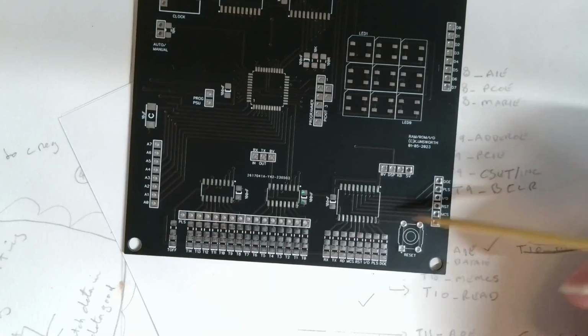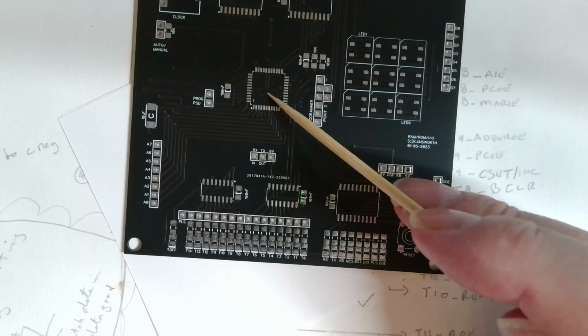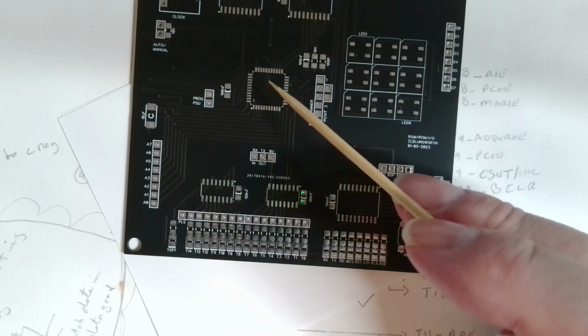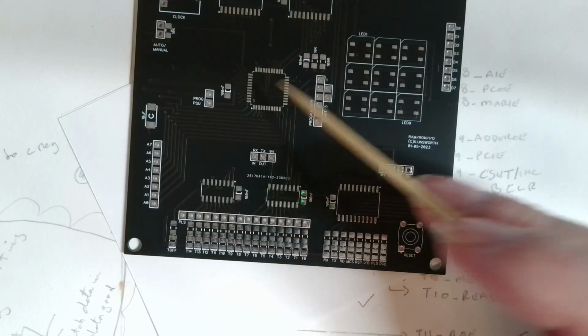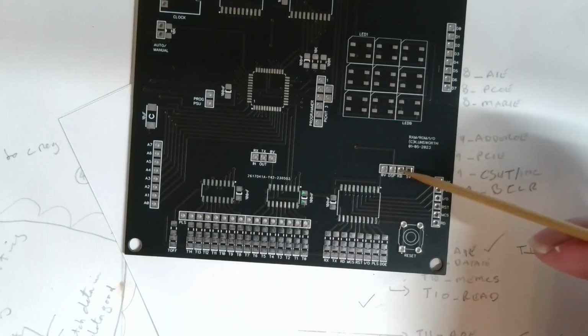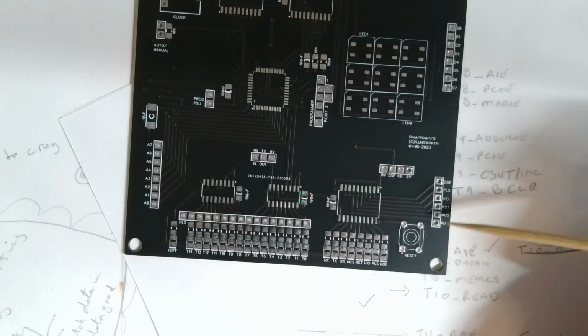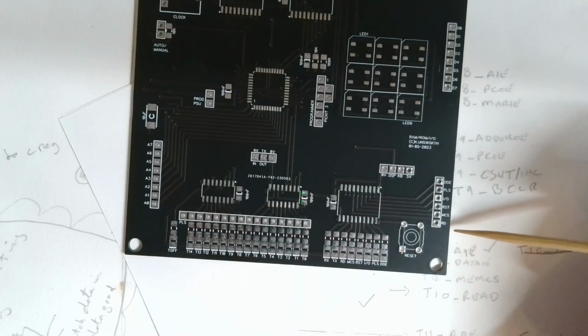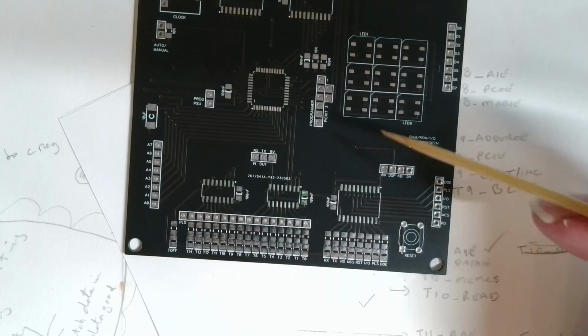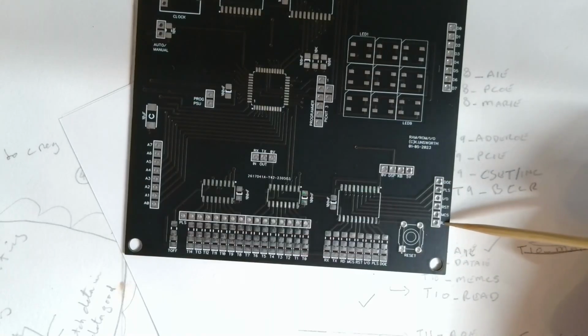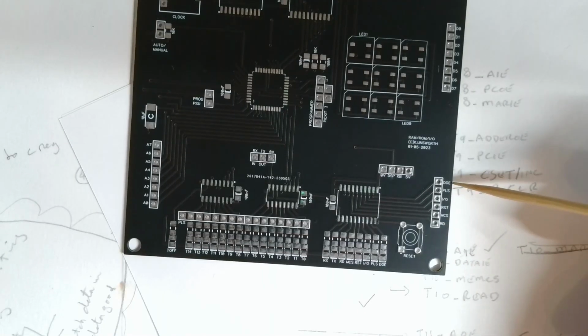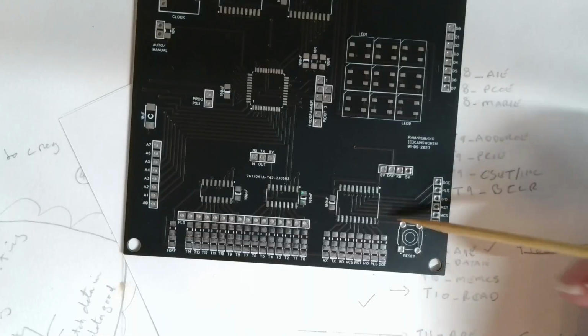So you need both of those signals coming into here, so it knows what to emulate, whether to emulate memory or I/O, because the I/O is used for the video and the keyboard and the paged memory. And the bottom one is the read signal, to let you know whether it's a read. So that's your read, and that one's your write, basically. The read is coming in as well.